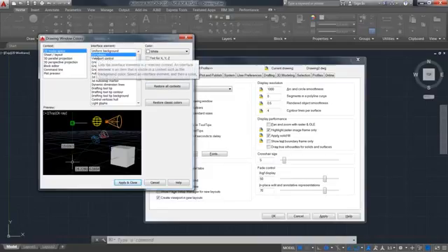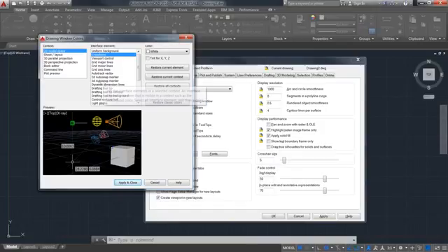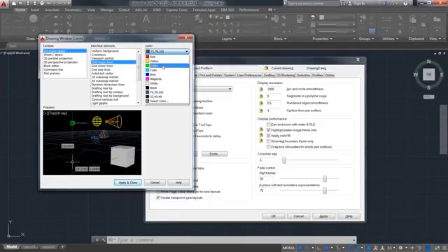You can change the colors of your crosshairs, you can change the colors of the sheet and layout, and you see back there behind all this there's a grid over the entire drawing area. You can change the colors of the grid lines to really exaggerated colors. We'll do that just to see what that looks like here and make it as obnoxious as we can.